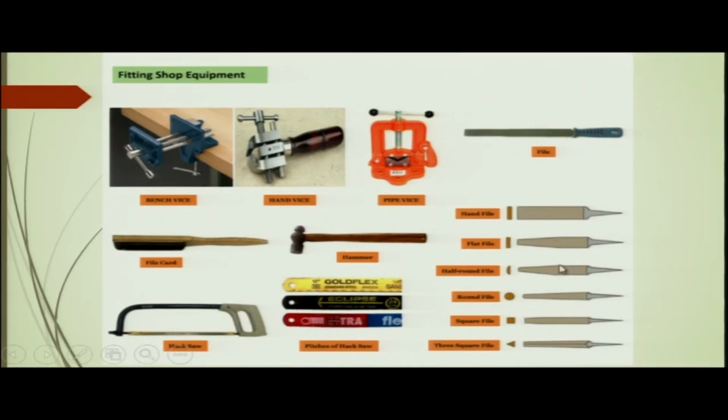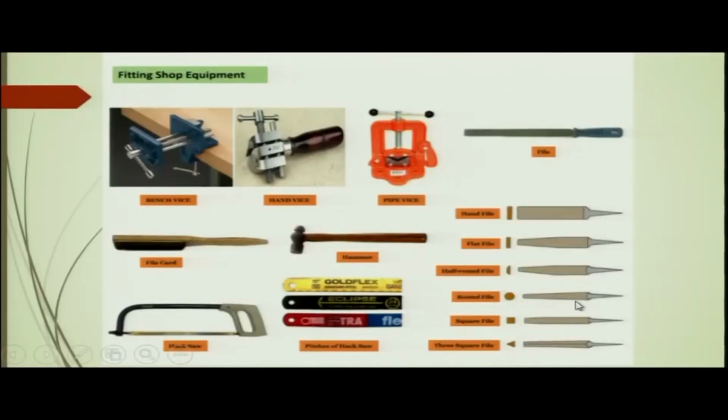This is a half round file. So, half round file will serve the purpose of a flat file as well as for the round shape holes or slots, for example. Round files are exclusively used for filing the inside of a hole.